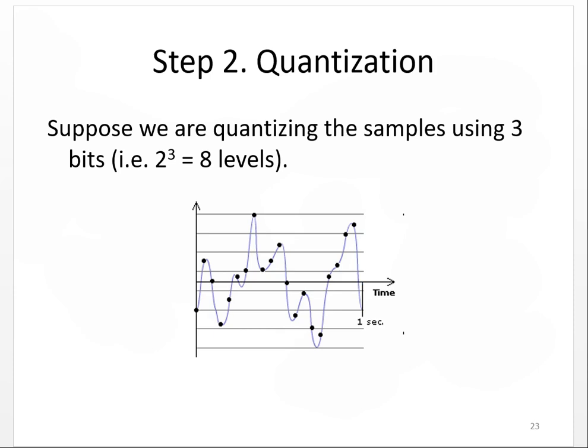Here we have an amplitude figure. It is not yet rounded off, we need to round it off. It can be rounded upward, so it may be near to this one, it can be rounded off with this one. So what we do is just round off. Let's say this value is 1.8 and this is near 2, so we can say it's 2, and this is roughly 1.9, so we can say it's equal to 2. This is called quantization: making an amplitude value a rounded value. Rounded values mean 1, 1.5, 2, 2.5, 3, 3.5, 4, 4.5, and so on. This is the way we make a quantization.